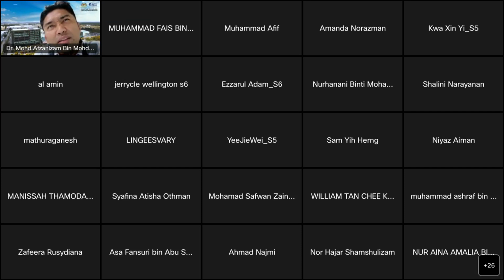Chow, can you just give a brief statement, maybe in 30 seconds, what you have learned today? The new tips that you discovered by having this kind of session, just to share with the others. So today we learned that based on the number of solar modules, we choose the most appropriate inverter, and then we arrange it in series and parallel. Then after that, we choose which one is the most appropriate configuration.